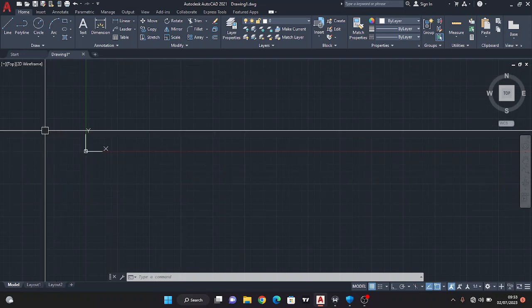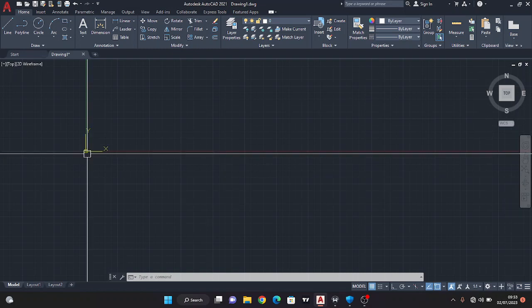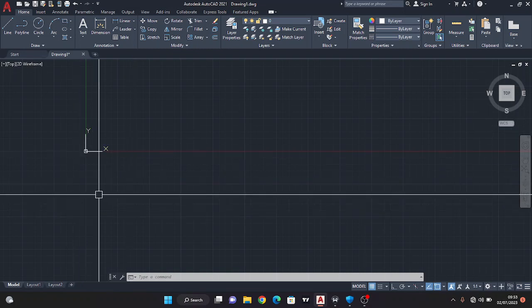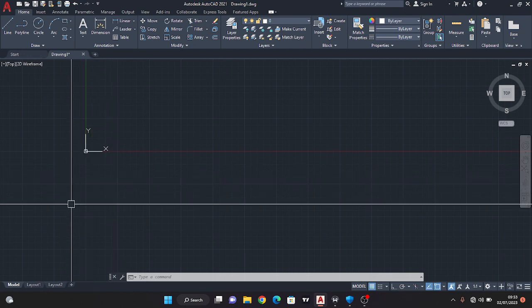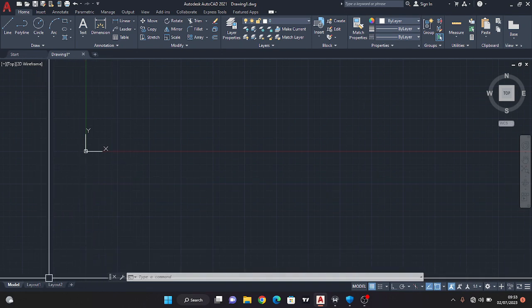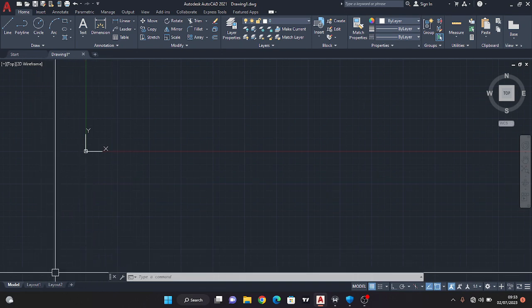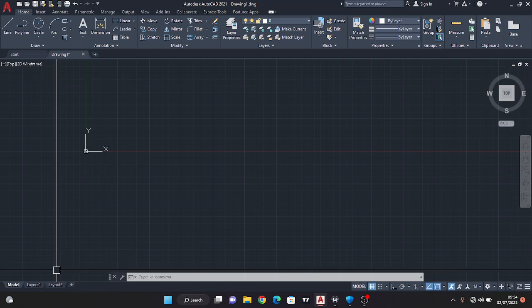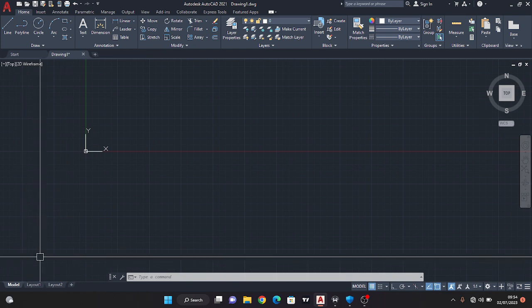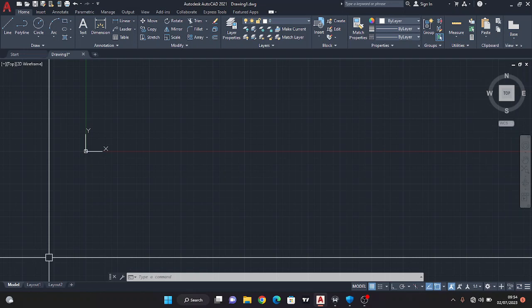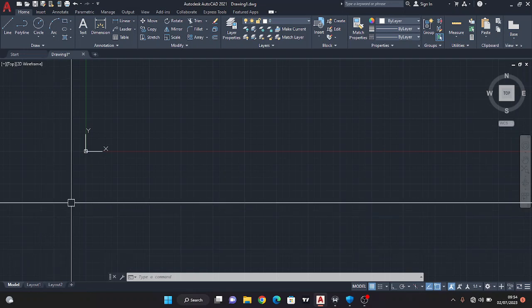But firstly, if you open a page, what you really need to do is to set up the page, because you can't work on this. It is a dimensionless page. There's no unit attached to it, though there's a unit attached by default, and that default is not exactly what you want to work with. Most of the time you can go from meter, millimeter, centimeter, feet, inches. You understand? But majorly, drawings in this region are mostly featured in millimeter and feet. You understand?